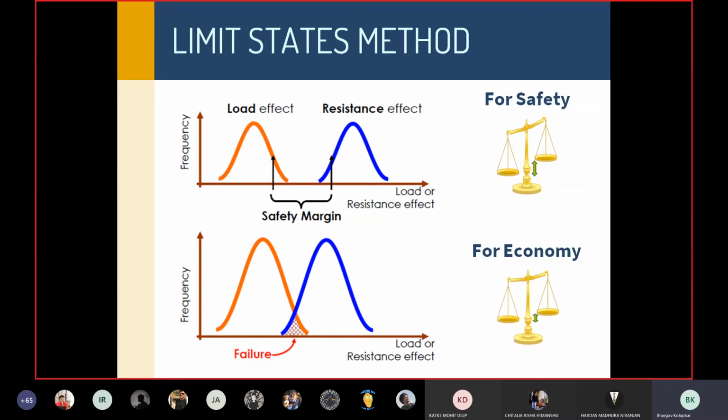So we try to design it in such a way that it is safe and serviceable. The graph that you see on the lower portion suggests that there is only a slight possibility of failure of the structure. That is when, on one of the 100 days, the loading is more than the characteristic load on the slab, which is designed from the concrete which has the strength of the five blocks that we say are failing below a certain value. So we are targeting that possibility of failure.